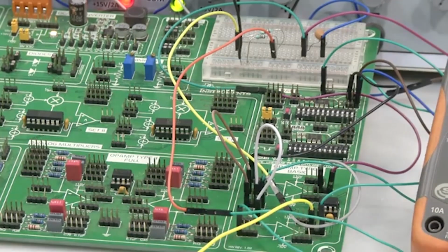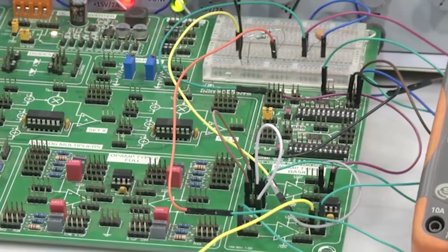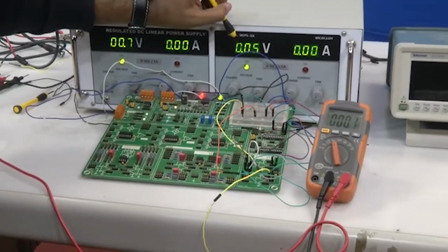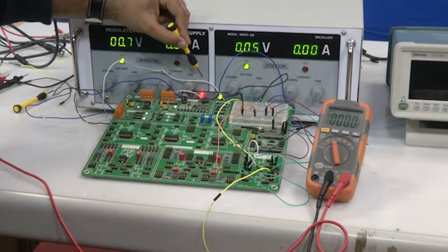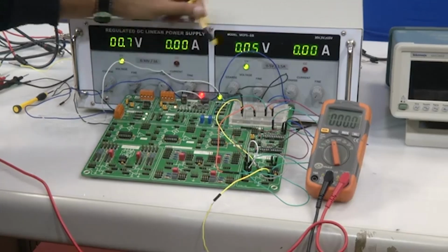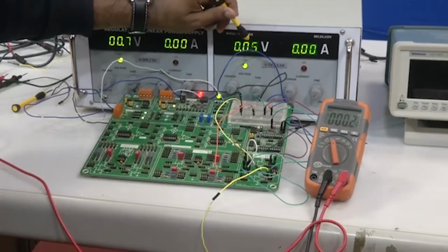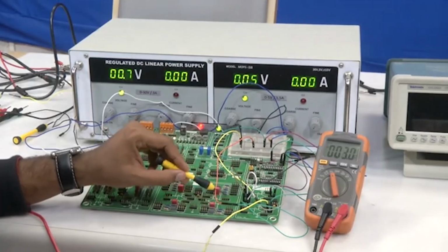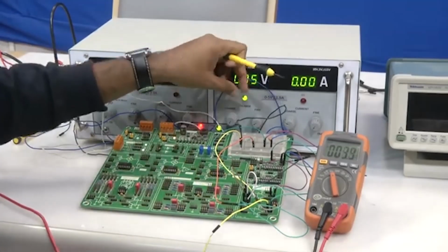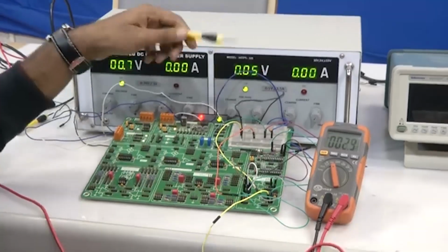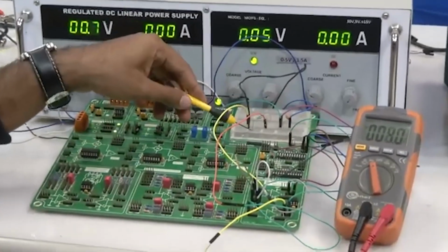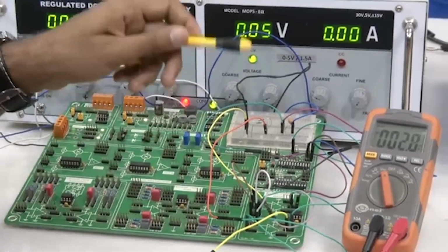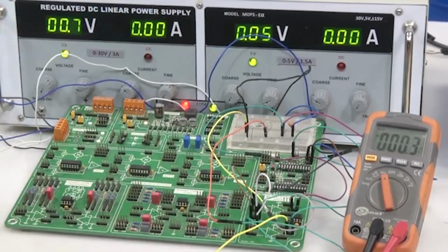So, let us see how by changing the bit sequence we are able to see the change in the output voltage. If you see the power supply, the input voltage is applied from this power supply. The plus 15 minus 15 supply for the op amps is given from the central power supply. We are applying an input of 0.05 volt or 50 millivolt, and that signal is applied through the resistor here. Then we will see the output by looking at the output of the op amp.